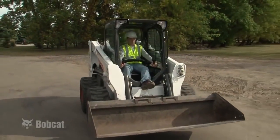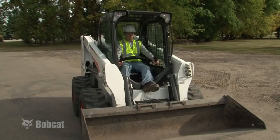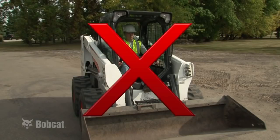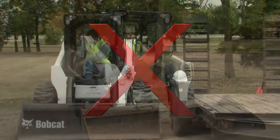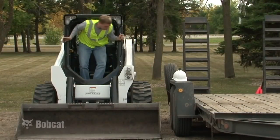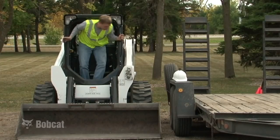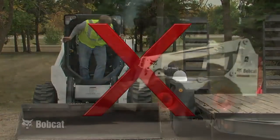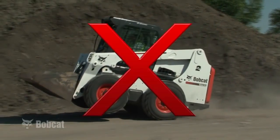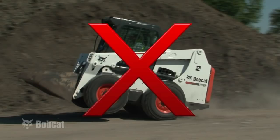Operate the controls smoothly, keeping your hands on the controls and your feet on the foot pedals or foot rests at all times. Never stand, lean, or reach out of the front of the loader when the engine is running. A steering control or hydraulic control could be activated. Don't make any sudden stops, starts, or turns. Again, operate the controls smoothly.